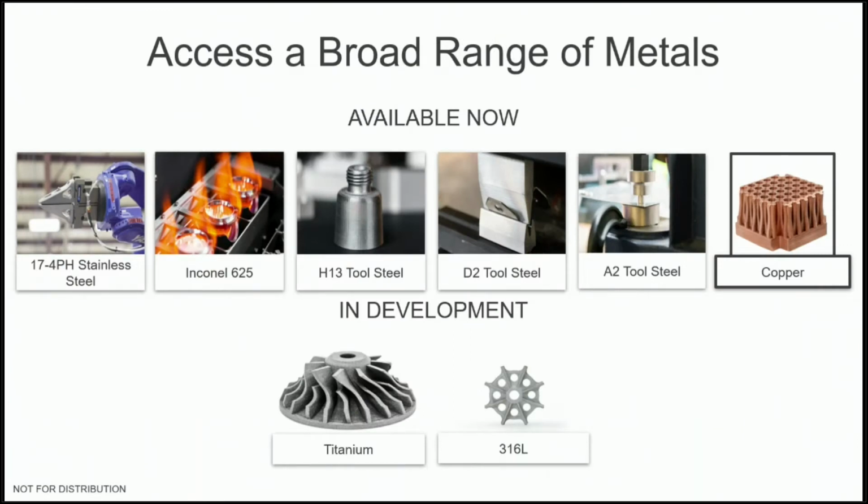Currently our materials that are available are 17-4, Inconel, tool steels in H13, D2, A2, and newly shipping is copper, which is a very interesting material. We also have in development titanium and 316L, another blend of stainless.